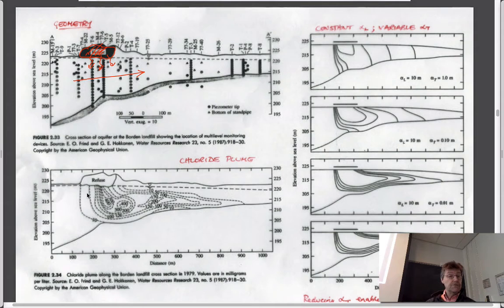So if it was diffusive only, you could imagine, I suppose, that the plume might look like this because it's going in each of these directions. But if it has this big component which is in the rightmost direction, then you could pretty much conclude that it's, if not advection dominated, it at least has a significant component of advection that's carrying it down gradient.